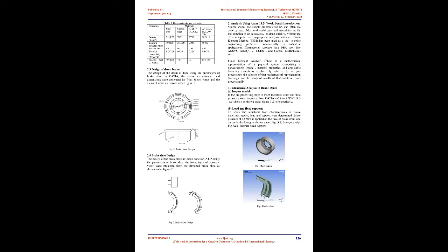Due to the applied brake pressure, the kinetic energy of the vehicle is converted into heat energy at the road wheel. The energy absorbed by a brake depends upon the type of motion of the moving body. The motion of a body may be either pure translation or pure rotation or a combination of both translation and rotation. The energy corresponding to these motions is said to be kinetic energy. The energy absorbed by the brake and transformed into heat must be dissipated to the surrounding air in order to avoid excessive temperature rise of the brake lining.